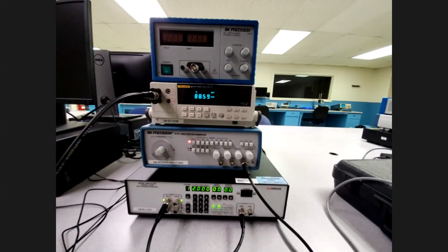Okay. Because the oscilloscope has the unfiltered signal, it doesn't matter if we increase the frequency, it's going to remain being the same peak to peak. That signal from the oscilloscope is unaffected by the filter. So again, peak to peak from oscilloscope, 10.4. And from the multimeter, we have 0.08 volts RMS.